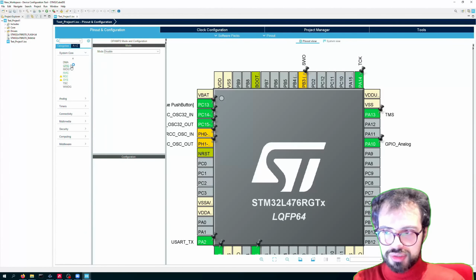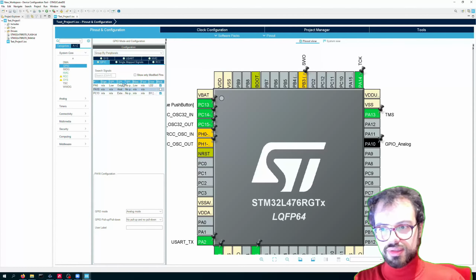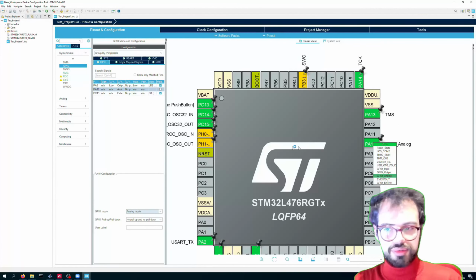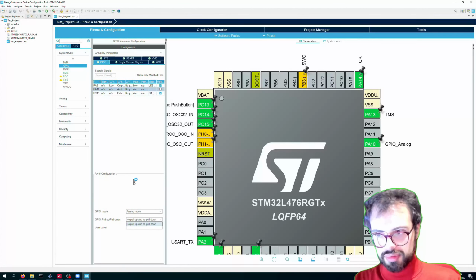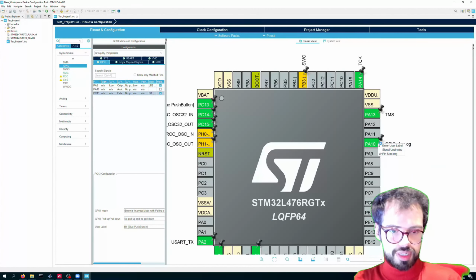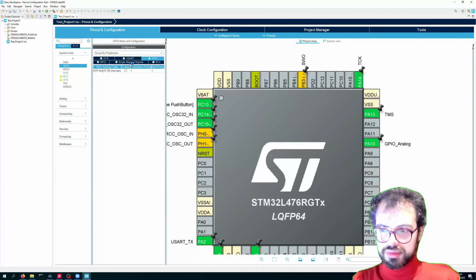Last thing that I want to touch here is GPIO here. You can modify in a more specific way all the GPIOs that you have enabled manually here. All the modes here. I guess for instance analog mode you have to modify it here, of course, but you can choose a pull up and pull down resistor, for instance here. You can put a label, which you can do also with the right click here eventually if you want. And you can enable the interrupts here also.